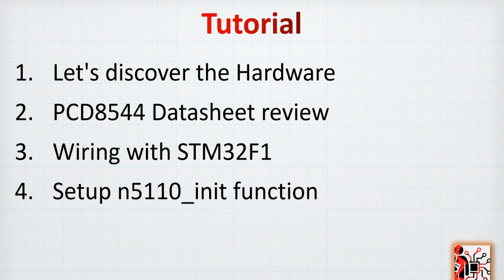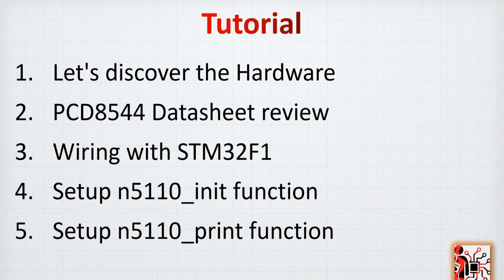After that, we have to start making the setup function. We will call it the N5110 init function, where we will initialize the screen with the STM32F1. And finally, we will have the N5110 print function to print our hello world.